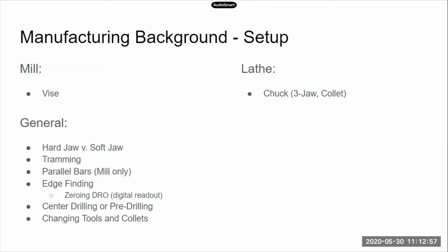Like I said, once you have it on the machine, there's some parts that slow it down, but a lot of that's going to be figured out by whoever's manufacturing it. So they'll figure out, oh, these are the speeds I need to use. But on your end, if you can make their life easier by making a part that has edges to clamp by, that's helpful.